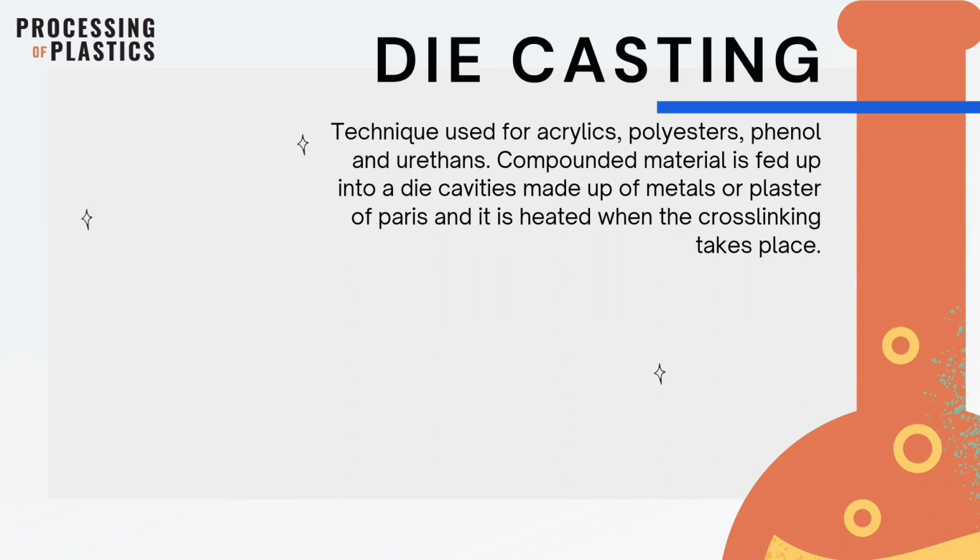Here, reusable steel dies or molds are preheated and coated with a die release agent to lubricate and protect the surfaces of the dies before each use. Next, pre-measured amounts of molten metals are injected into the die at extremely high pressure. The newly formed part is then removed from the die and the cycle is repeated after it cools. The die must be stronger than those used in the permanent mold process to withstand the high pressure injection. These can be engineered to produce complex shapes with a high degree of accuracy and repeatability.